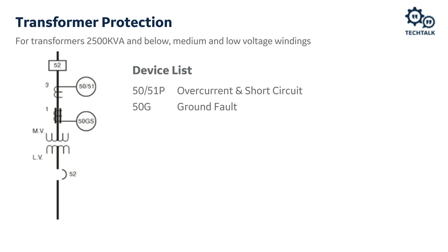So here we're just providing basic protection. Being that these are the most basic overcurrent functions, in a lot of cases you'll see either just a small transformer protection relay or even a basic feeder protection relay whose primary function is to provide overcurrent protection. Feeder relays often end up at a lower price point than transformer relays, so for low voltage applications, you'll often see feeder relays instead, but either way, the 50/51 functionality is the same.